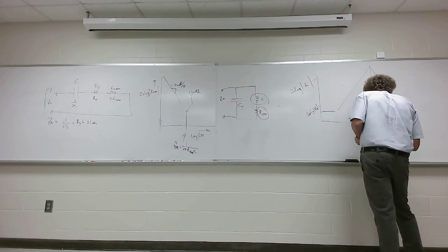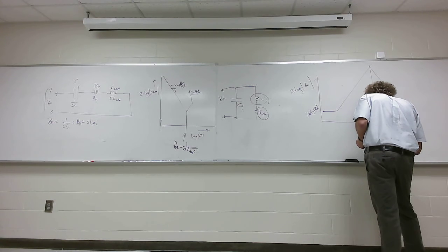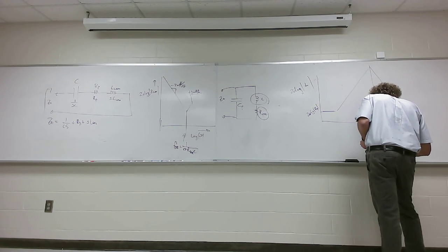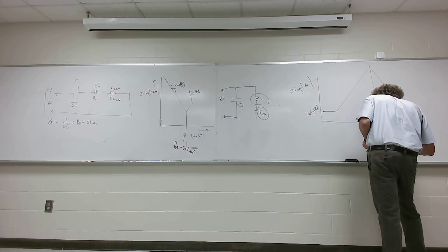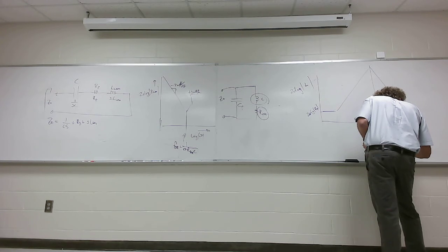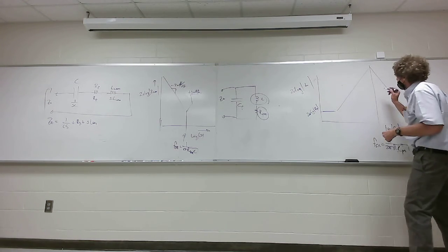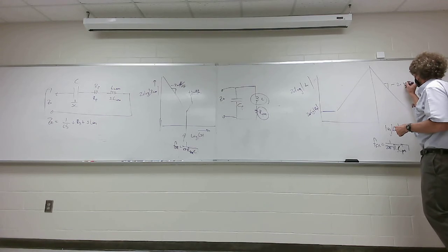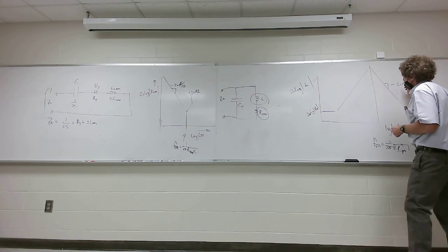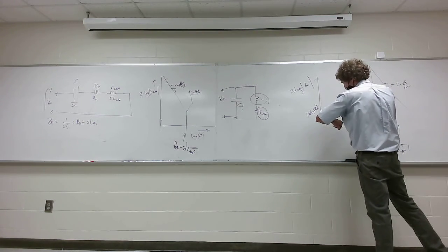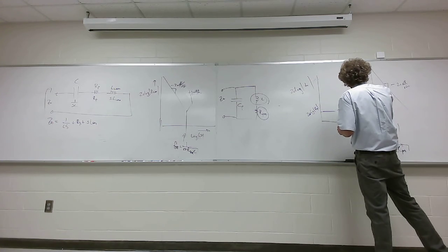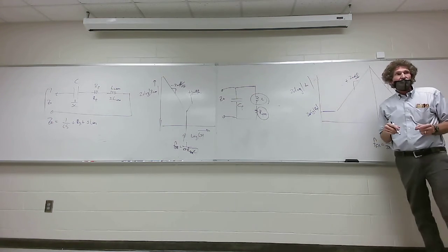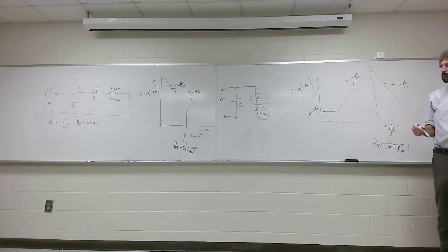Here's what you're worried about, the self-resonance. And that's equal to 1 over 2 pi square root of LC, and this is L lead, or L itself, the actual value of L, times C parasitic. And this is shown. And this is going to be minus 20 dB per decade, and this is plus 20 dB per decade. Y'all with me on that? Now those are the 3 plots I wanted to get up there. You can do the math on that and show it.